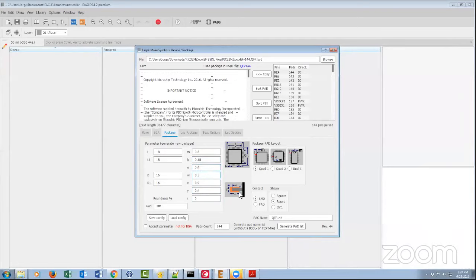Okay, so what we have to determine is, if you notice, the Y is super thick relative to the thickness of the pin. That's part of the issue we were running into before. So let's see if there's anything in the data sheet that can help us make this determination. The fact that they're a bit long is not really a big deal. It was really the width that was giving us trouble. So we've got to check this Y value. Right now, Y is 0.4, the thickness is about 0.2, and the pin pitch is 0.4. As you can see, it's really, really tight.